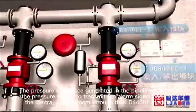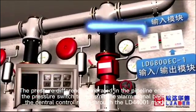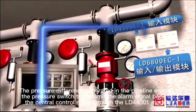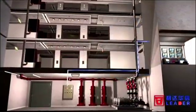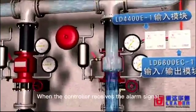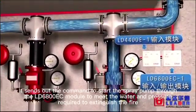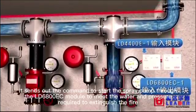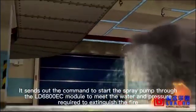The pressure difference generated in the pipeline enables the pressure switch to transmit the alarm signal back to the central control room through the LD4401 module. When the controller receives the alarm signal, it sends out the command to start the spray pump through the LD6800C module to meet the water and pressure required to extinguish the fire.